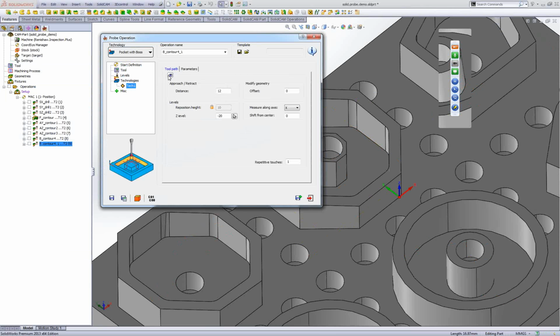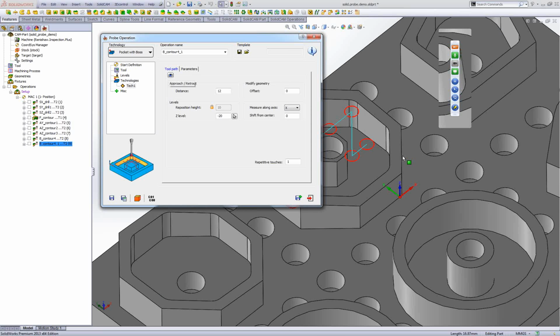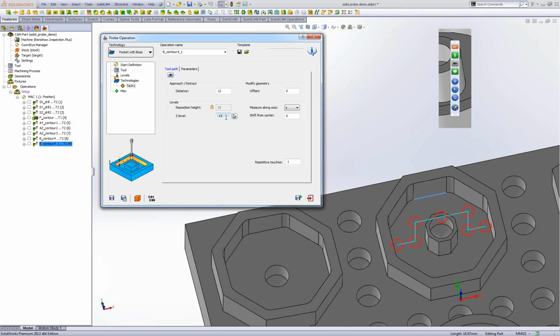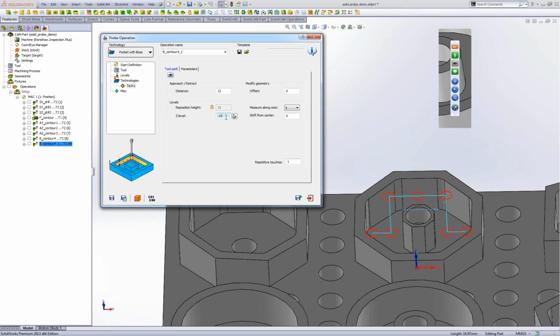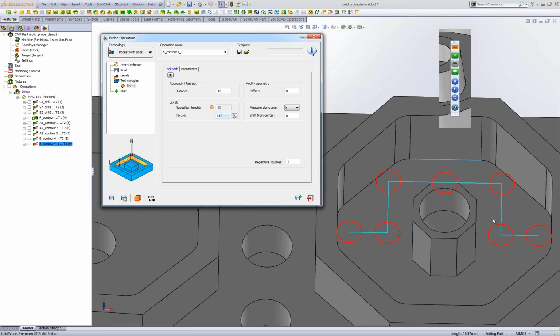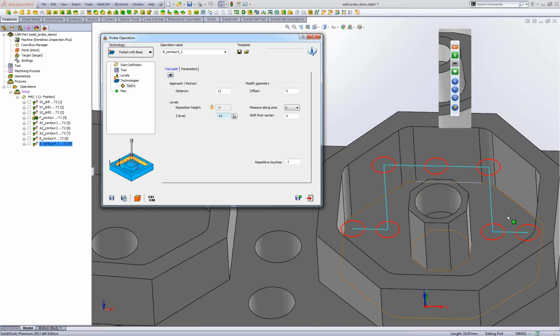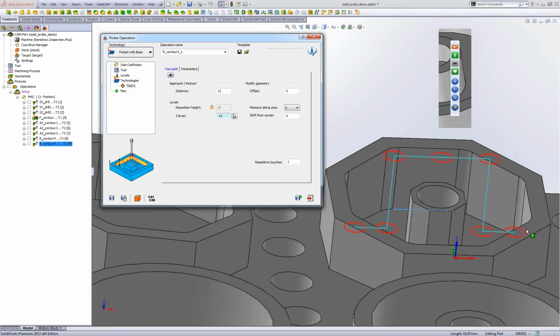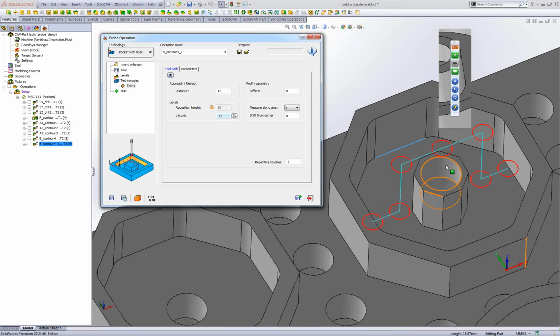The tool, I already have the tool. Yes, this is the toolpath for measuring a pocket with a boss. The probe will go down, touch the part, go up to the clearance, go to the next point, down, and touch the part to avoid the collision of this feature in the middle.